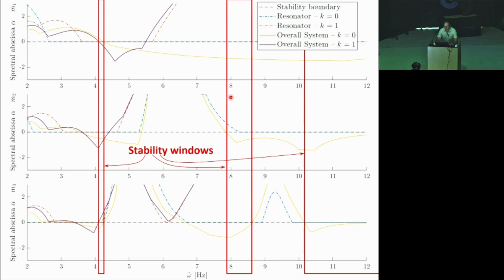Actually, theoretically, it would be better to validate the algorithms at higher frequencies, where by theory the system should be more stable, or it should be easier to stabilize it, but unfortunately it was not possible due to hardware limitations, because the delay was too small for our sampling rate of 1 kilohertz. So we just chose for validation the frequency close to 4 Hertz.